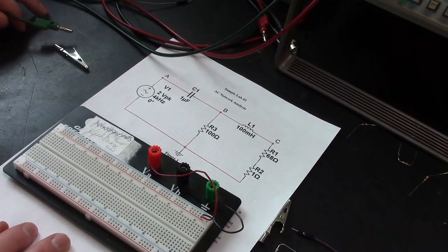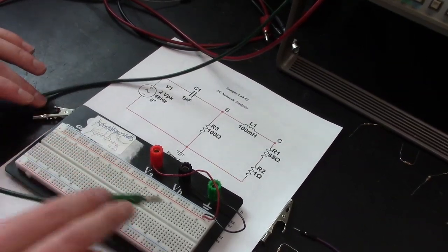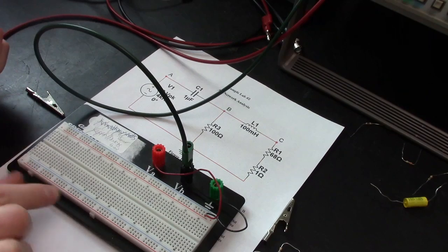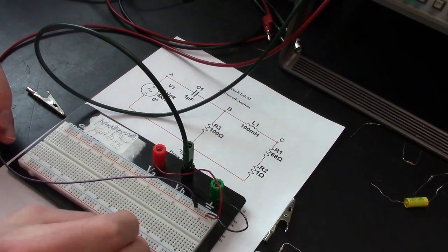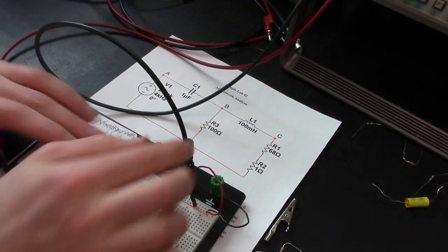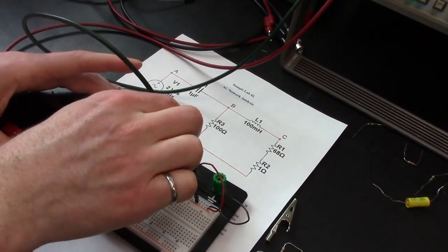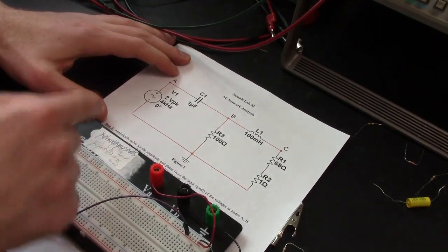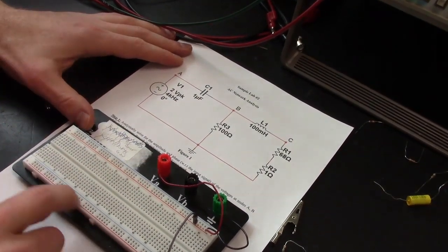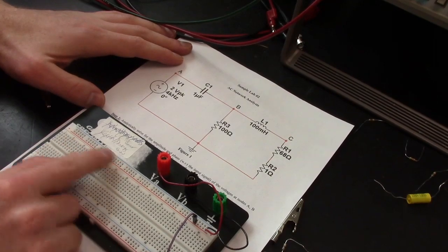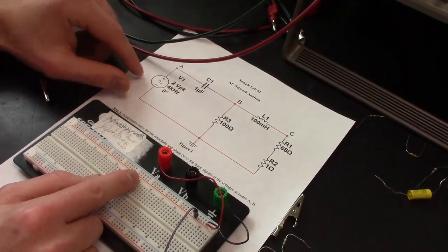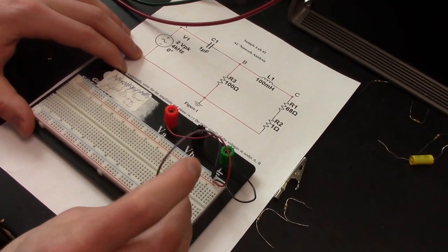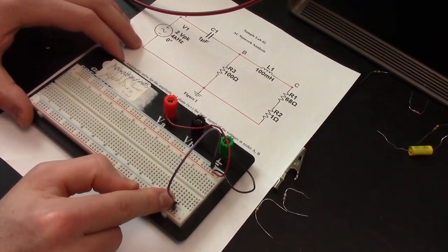Alright, so now we've got our circuit ready to build. First let's double check that the breadboard terminals are connected to what we think they are. So the negative should be connected up to the negative here. Yep. And the positive should be connected up to the positive rail. Alright, we're good to go. Now for this circuit, it's going to be easier to visualize if we make use of the bottom negative rail and the top positive rail for the other side of the voltage supply. So let's go ahead and use a jumper wire to connect the negative rail from the top to the bottom.